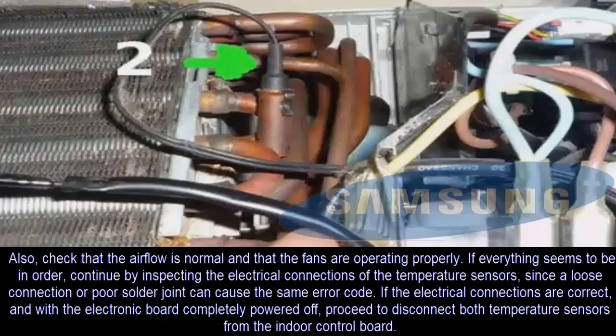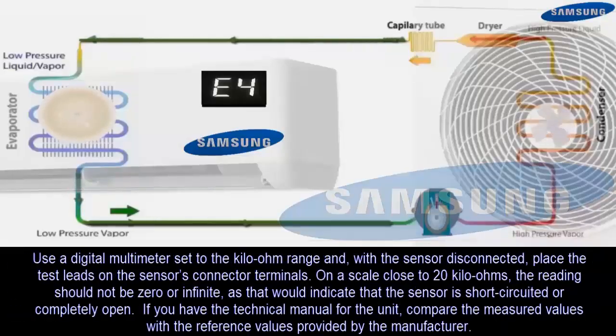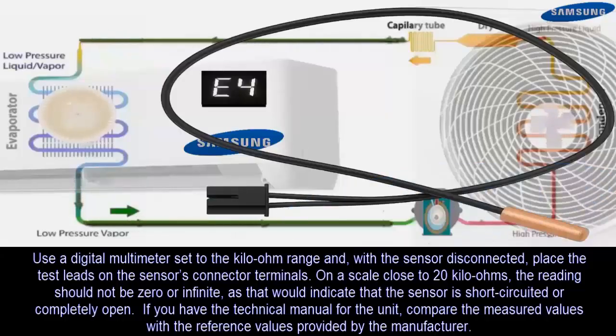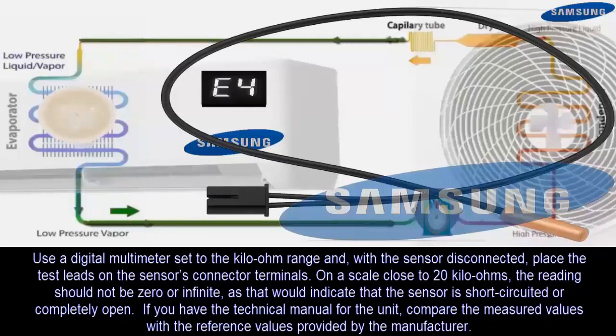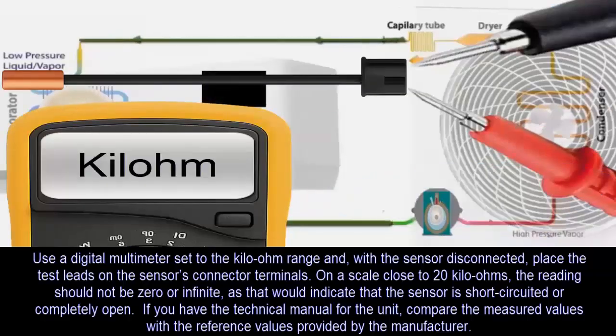If the electrical connections are correct and with the electronic board completely powered off, proceed to disconnect both temperature sensors from the indoor board. Use a digital multimeter set to the kiloohms scale and, with the sensor disconnected, place the meter's probes on the sensor's connector.